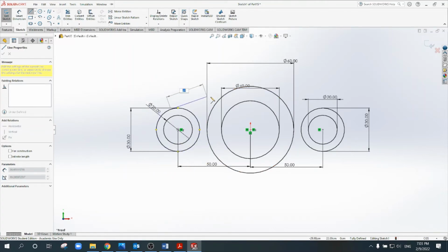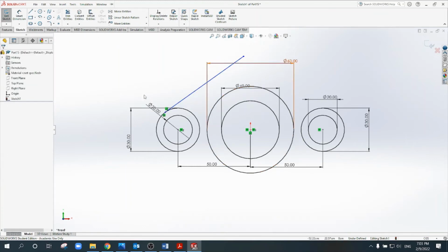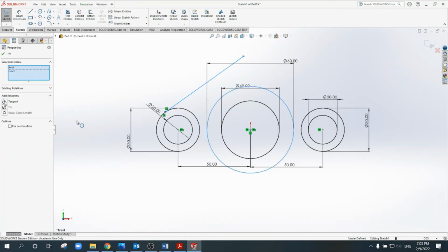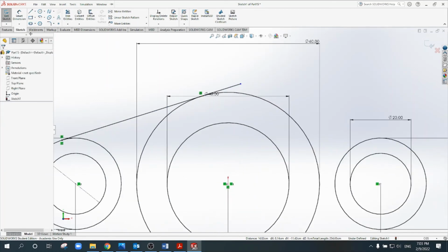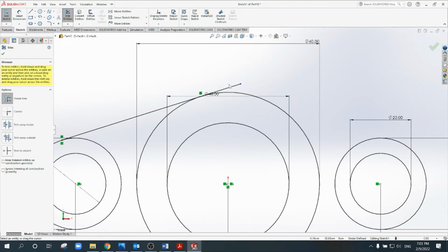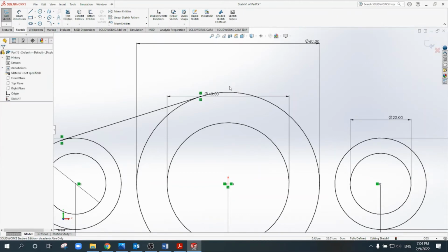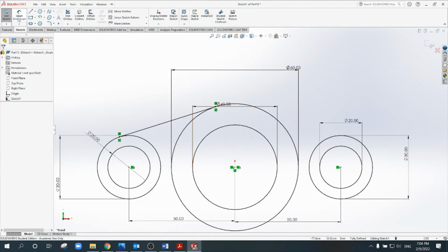If I want to stop, I cannot stop at this point because I can see that it's an intersection relationship, for example. Now if I go to a specific location, I can see the tangent relationship in the pencil, or I can stop anywhere, for example, and then I create the relationship between line, control, circle to be tangent. In this case I have to zoom in, I have to trim the end of this line. So I have to do this 4 times.